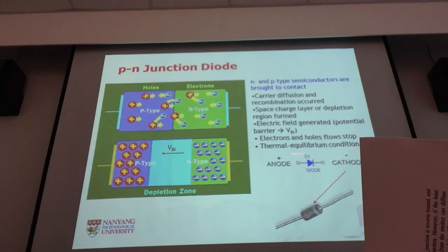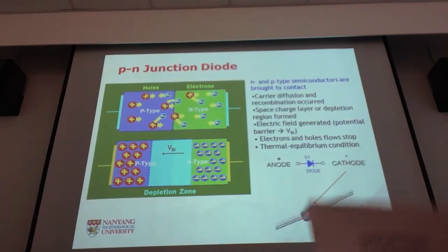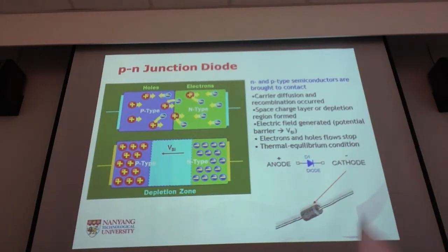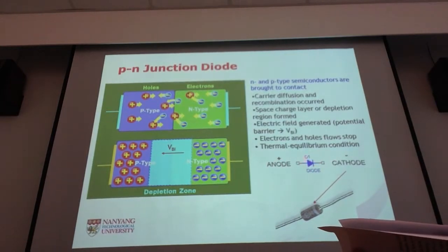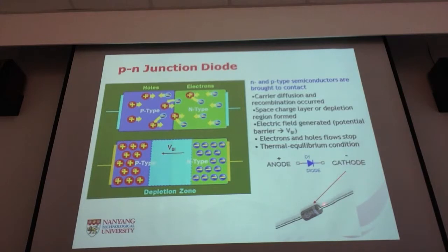And this is how a PN junction diode looks like. You will have a look then at the real part. And remember that in the circuit, the diode goes from anode to cathode. And the cathode here is indicated by a blue stripe here.